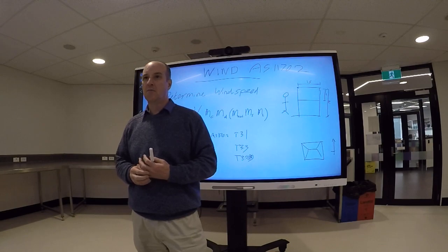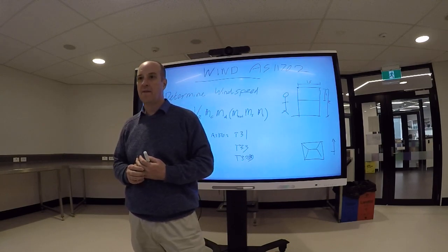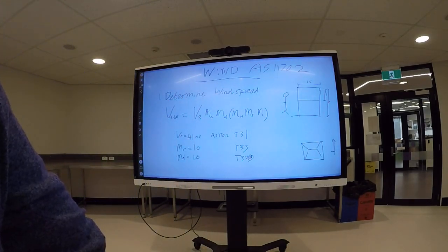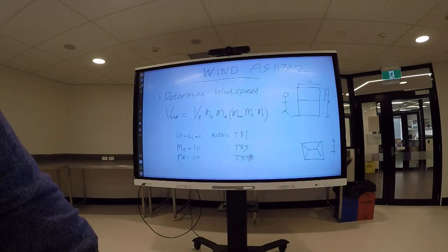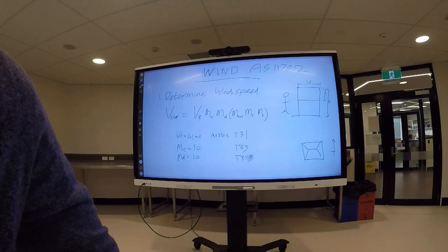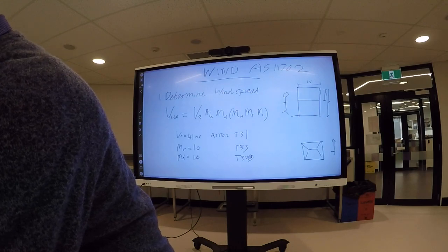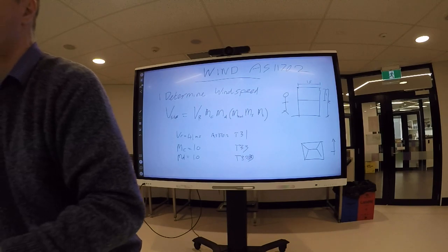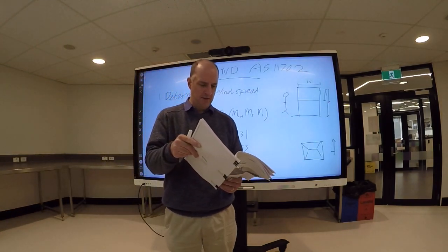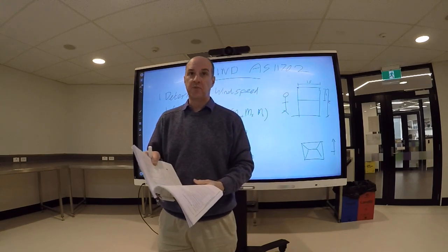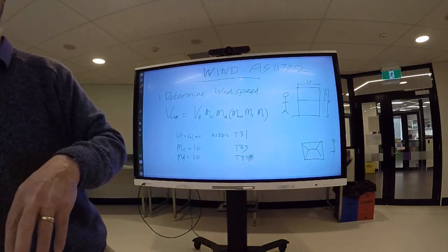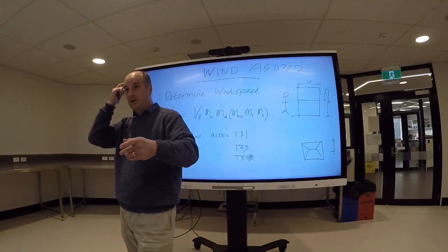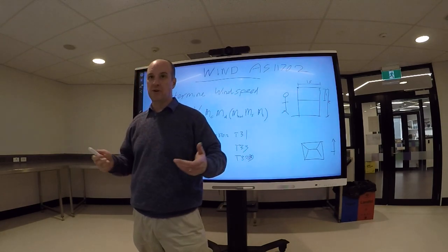2.5. Yep. Why is that? Looking at my notes. Yep. 2 is open terrain, grasslands with scattered obstructions. 2.5 is terrain with trees, isolated obstructions, large acre development, fewer than 10 houses per hectare. Yep. And terrain category 3? Yes, okay. If you're in a well-forested area, you could be in a 3. If there's trees here and trees there, you're more of a 2.5. Sorry? It's a 3 then, it's pretty well-forested.